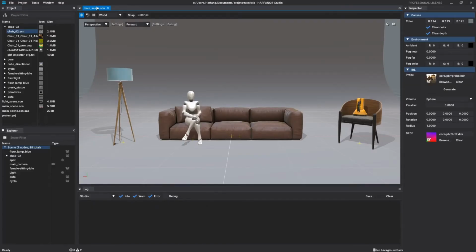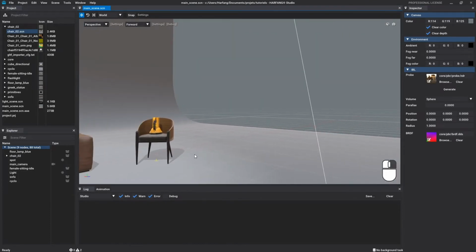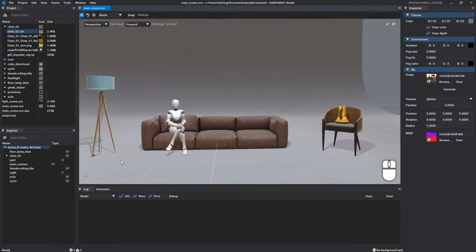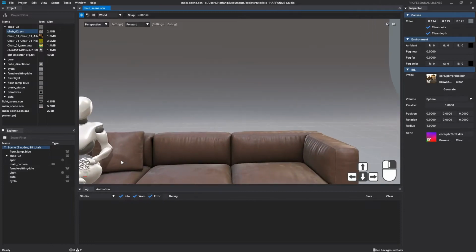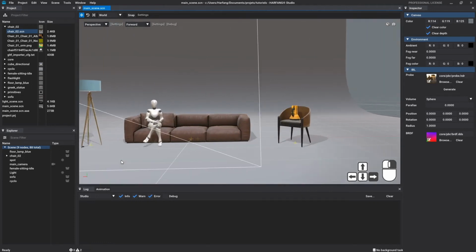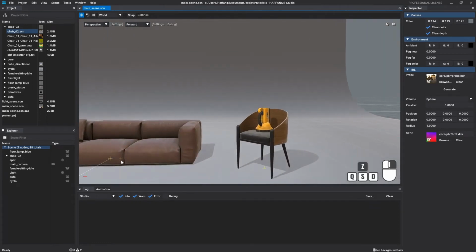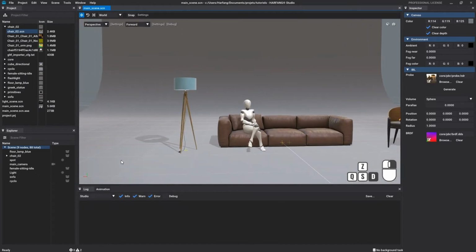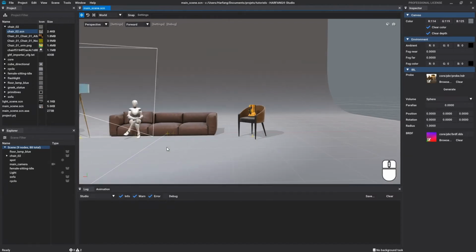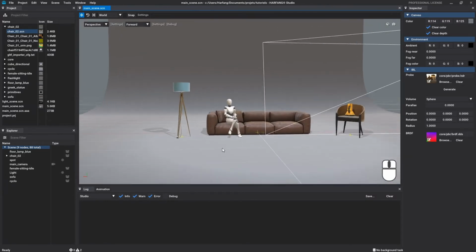There are two ways to control the camera, the keyboard and the mouse. Holding down the right mouse button will change the camera orientation according to your movement. You can use at the same time the keyboard arrows to move through the scene. Up to move forward, down to move backward, left to move to the left, and right to move to the right. You can also use the ZQSD keys or WASD depending on your keyboard as an equivalent to the arrows. To simply zoom in and out, you can use the scroll wheel. Or click on it to strafe side to side.